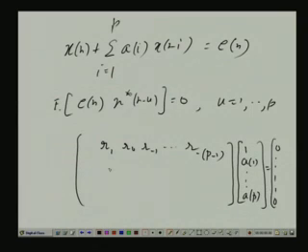Again I say it is not an Ax equal to 0 kind of equation, because you have got a 1 here which is a known quantity. So, 1 times R1 has to be taken out to the right hand side. If you do the first row times this column, you get one equation out of which R1 into 1 is a known quantity that can be taken to the right hand side. Same for other rows, you get a set of linear equations, solve them, and by solving whatever values you get, you plug in this model, you get a transfer function. So, you know the mod square of the transfer function times the variance, some constant, will be the power spectral density. So, basically you have to solve these equations.